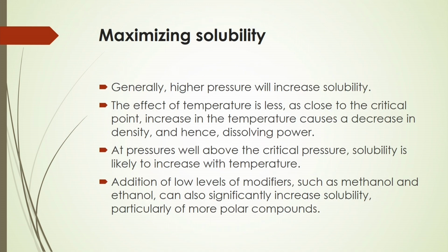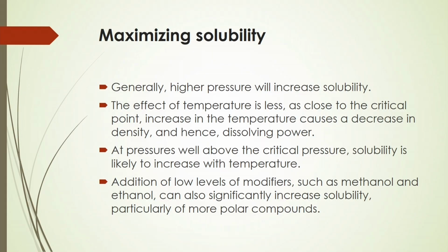You can also maximize the solubility. Generally, high pressure will increase solubility, and at pressures well above the critical pressure, solubility is likely to increase with temperature. Addition of low levels of modifiers such as methanol and ethanol can also significantly increase the solubility, particularly of more polar compounds.